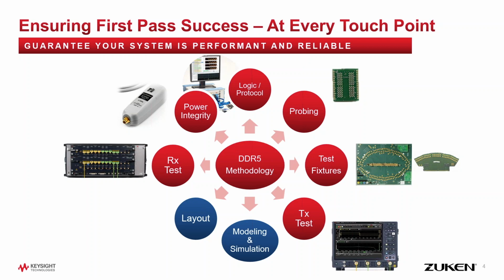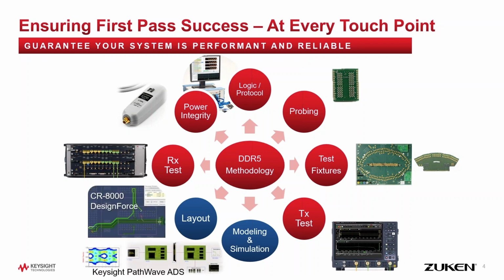But sometimes signal integrity on your PCB is not only about the channel, it also matters for the power planes as well. So the noise on the power planes and how they affect signal integrity, we need to be able to measure that power noise first. So we can do that with these very low noise probes, as well as they're designed to be able to connect into power planes that have a very low impedance. But mostly what we're going to be talking about today in this webinar is physical layout, which we're performing with CR8000, and modeling and simulation, which we're performing in Pathwave ADS.